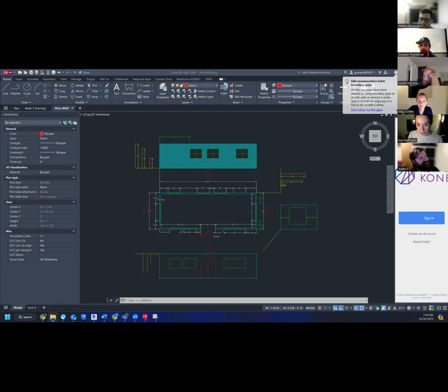Ultimately, I need to be able to take your plans and say, can I build something from this? Understand where the windows go, where the doors are going to go. If you just give me a plan view with no dimensions on it, that's cool, but I can't build off of this. I don't want to be going into CAD and making my own dimensions.